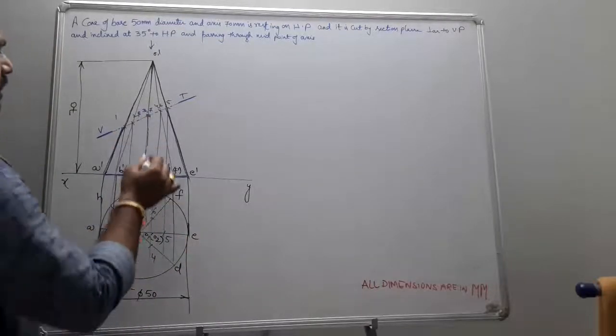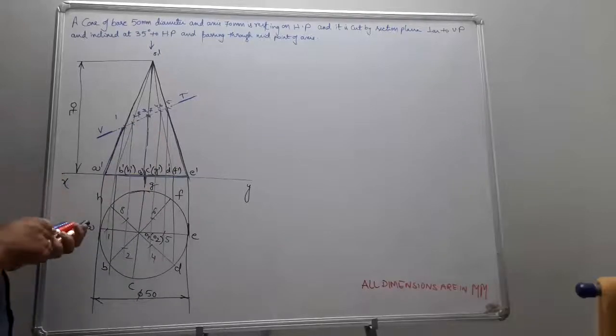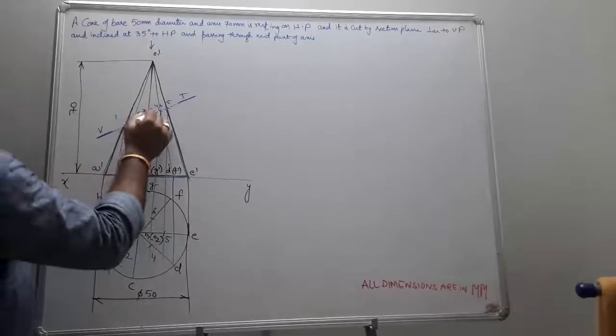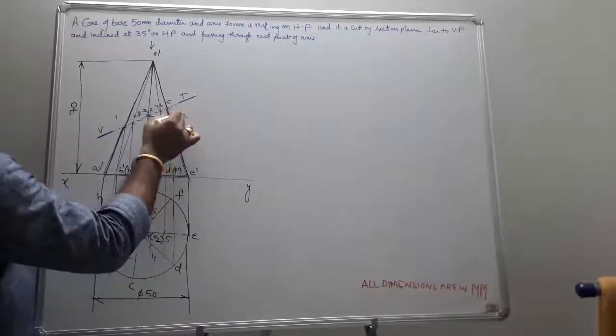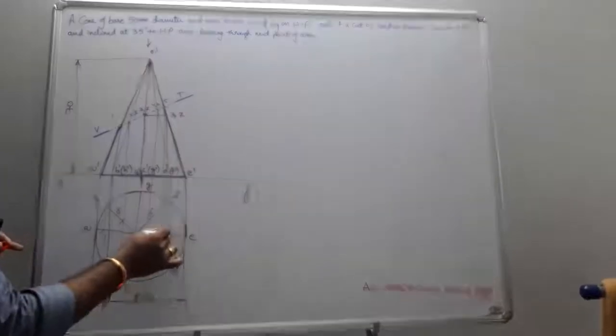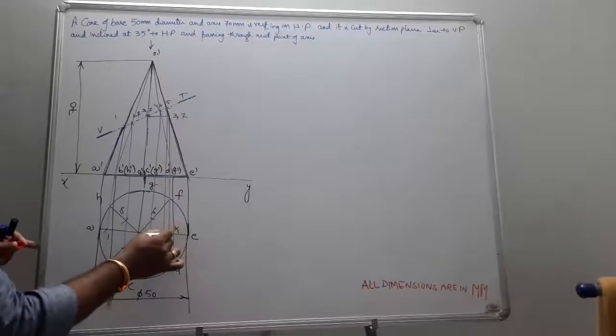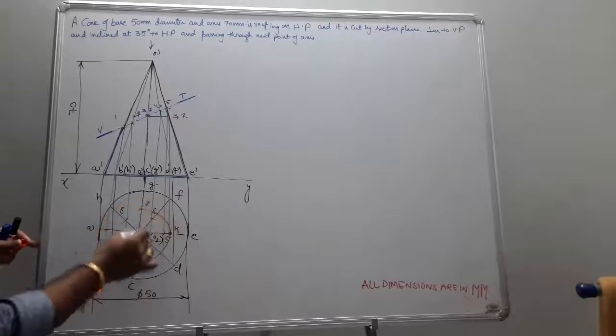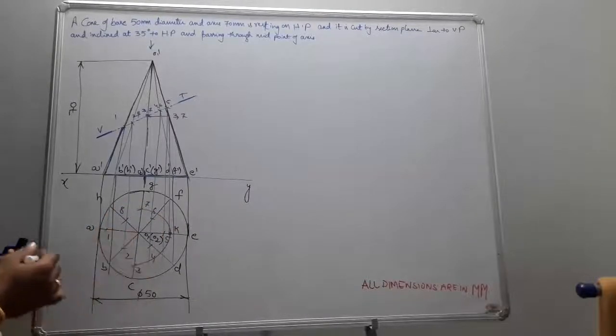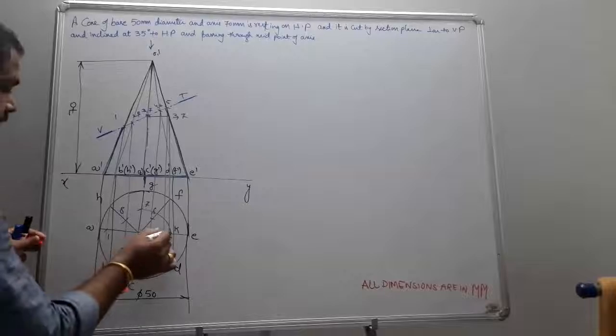So what you just have to do is project the points to the true slant edge, as we did in the previous class. This becomes my 3, 7. Project the point to the respective position, somewhere here. This becomes some K. If you draw to here, this becomes your 7, and if you draw to here, this becomes your 3. Now join all the points.